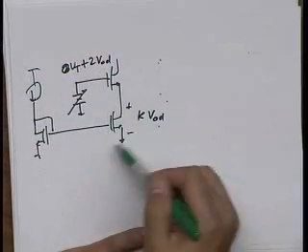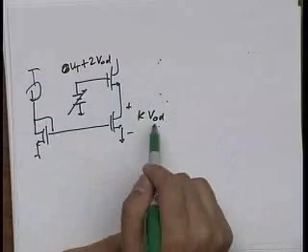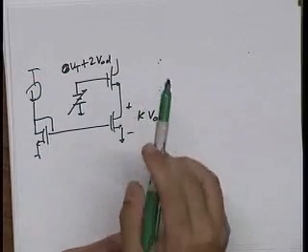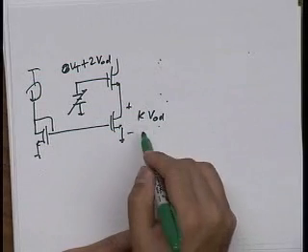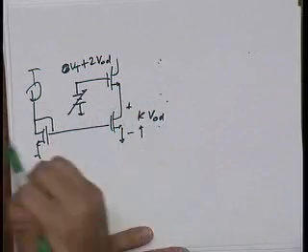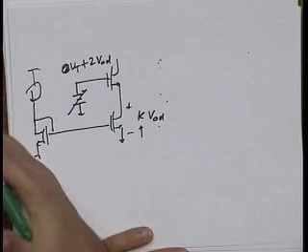But because this is a short channel device, the concept of overdrive is a little bit, you know, yeah. So maybe I need to have a little margin here. So I might make K 1.5. Or maybe I can be more aggressive and make K 0.7 or 0.8.